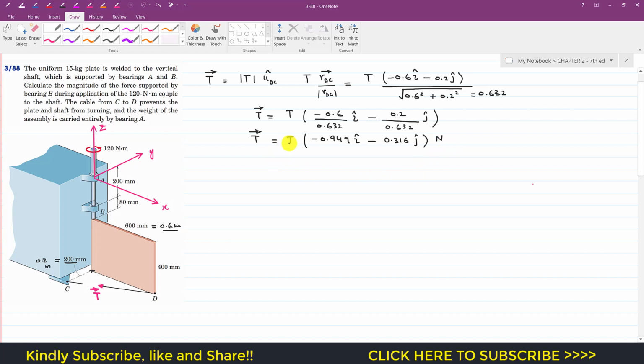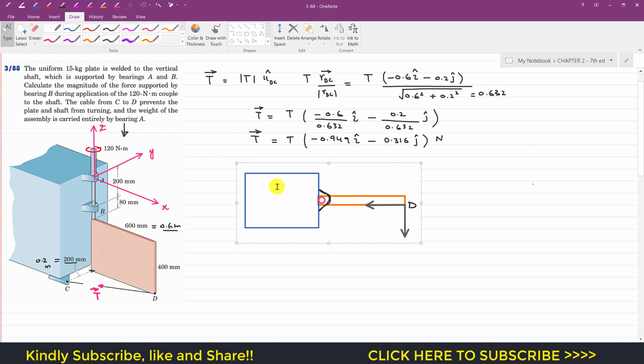Now we have to find the magnitude of this T. To find it, we have to consider the top view of this whole mechanism. If I observe this plate along with the shaft from the upward direction, that is the top view, we will have this as a free body diagram. We are looking at this whole mechanism from the top. This blue is the support, and this is the plate, and this is point D. So this tension T is from this point D to somewhere here.